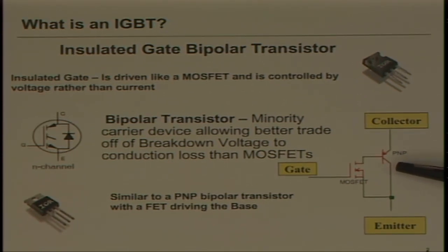So years ago we used to actually use these, more commonly the N-channel devices, and these would be the power transistor. One of the things you'll recall is that you have a junction drop here, so you get roughly 0.7 volt. It's actually the emitter of the PNP, but it's called the collector of the composite device. So how confusing is that, right? So it's the collector. In order to be able to draw current through the base, you need to have this low resistance MOSFET here. So the emitter here has to be at least 0.7 volt plus some additional drop lower than the collector. So there's no way you can saturate this thing to less than on the order of a volt. So that's a limitation to the on state characteristic of these devices.